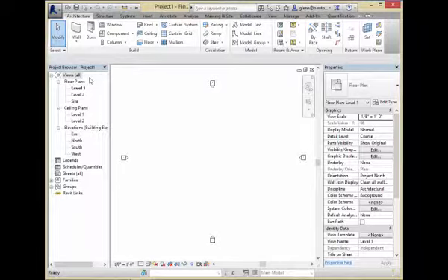So the subfloor is really just the layers of the framing, the wooden framing, some sort of joist or something like that. You'll have a layer of plywood on top of it. Okay. And that'll go over the entire foundation. We'll lay that out across the entire house. And that's what I'll call the subfloor. It really is just the framing and that little bit of plywood on top of it. On top of that subfloor, we'll actually put in finished floors. Okay, so on top of that, in some parts of the house, we'll put some wood in there. In other parts of the house, we'll put carpeting on top of that. Okay? But it tends to be two layers, the subfloor and then the finished floor on top of it.